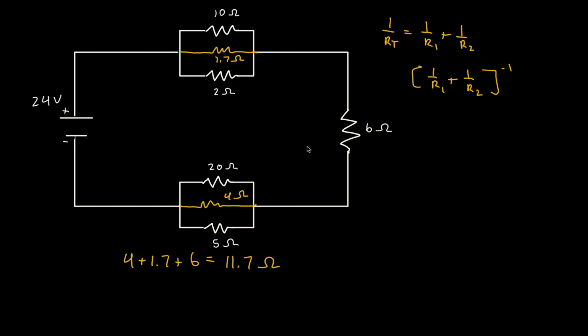So now we need to find the amount of current that is flowing through this entire circuit. Now, since we are in a series circuit, the amount of current that is flowing is going to stay constant. So then we can just pull out our Ohm's law, and we know our voltage, 24 volts, or I'll leave it as whole numbers just to make it a little bit easier.